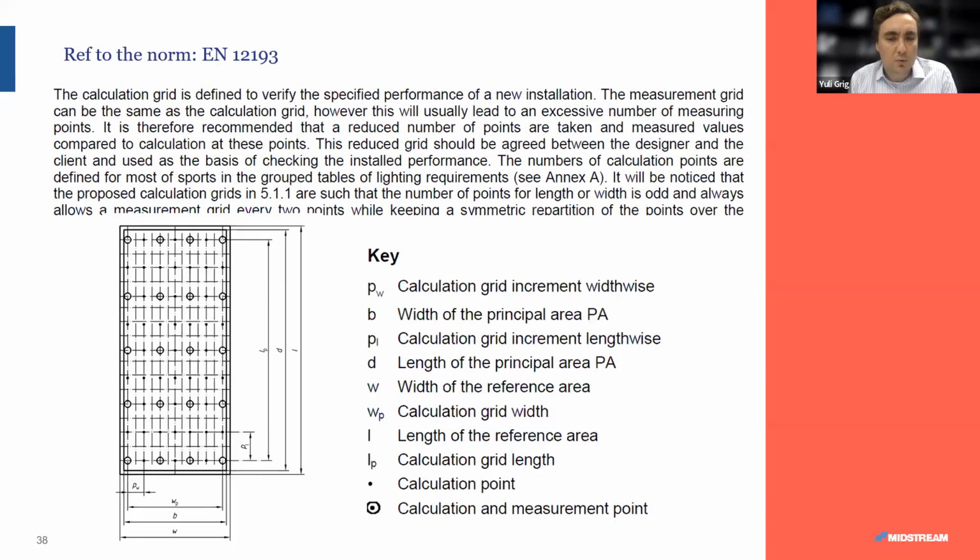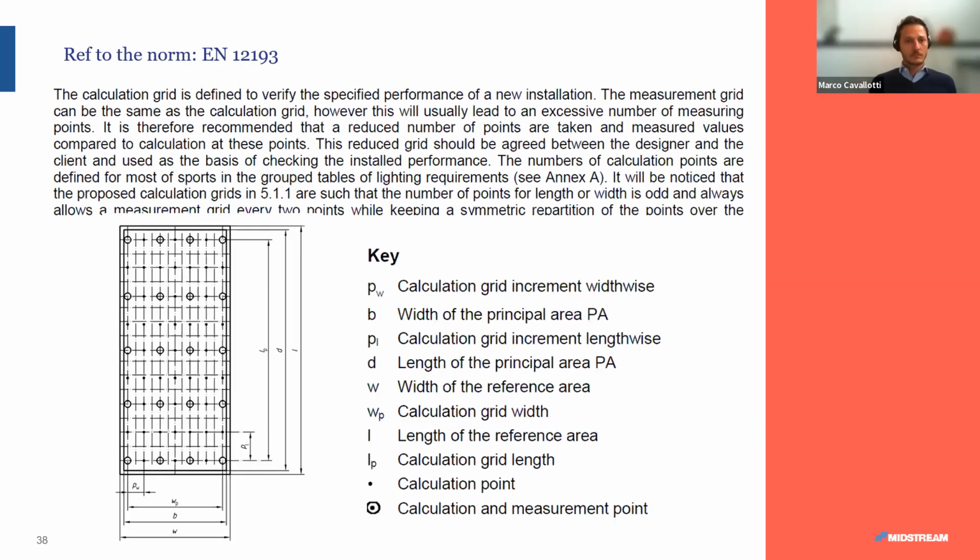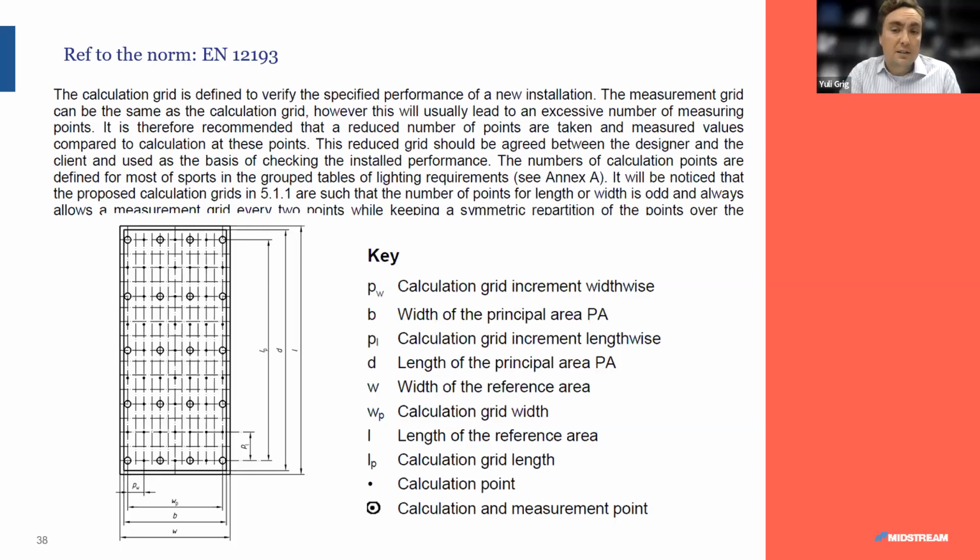Ultimately, an aircraft wing will always create a barrier to the light. It's not translucent. Light cannot travel through the wing or through the fuselage. So obviously, there's going to be some kind of shadowing. But we've employed 3D models for some airport customers in the past to show where those shadowing problems can occur. And how much glare value is allowed is another follow-on question. Well, as little as possible, but the standards refer to a GR value of 50 or less, which is something that we can demonstrate on simulations when we submit our design proposals to the customer.